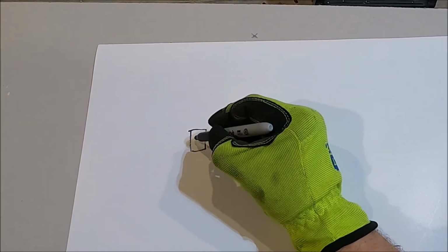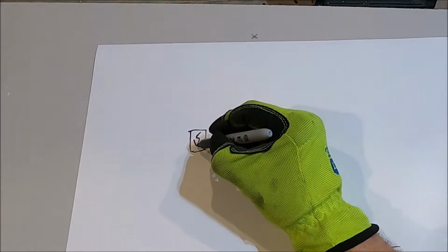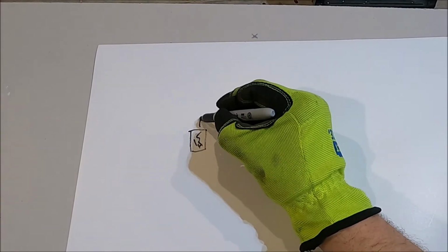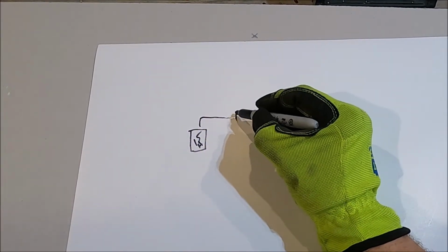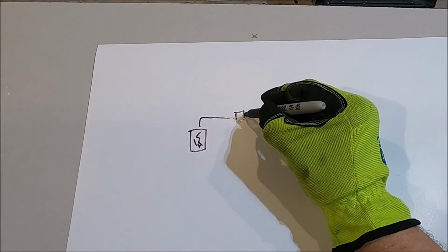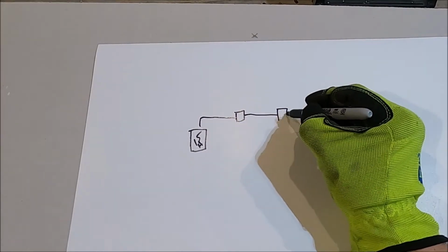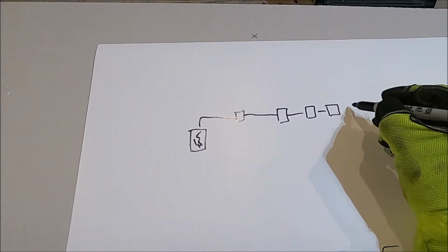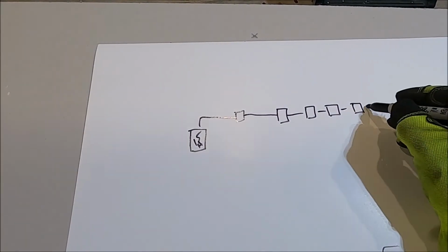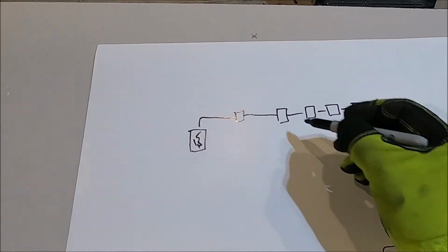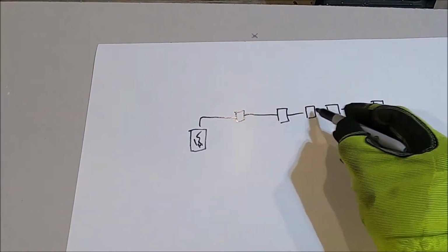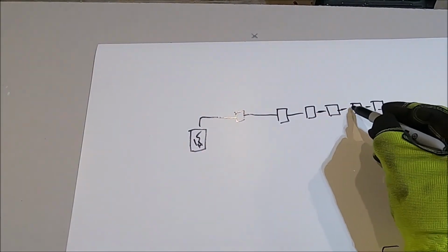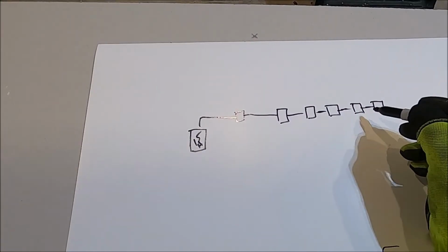So think about what I just explained. Here's our panel box with our breaker, 15 amp. We're going to run that Romex over. It's going to hit the first box. Then that hot wire is going to continue on, hit the second box, third box, over to the office, and then the next box, and then that double box. So throughout all of these boxes, there's always one wire in there that has power, the hot wire.